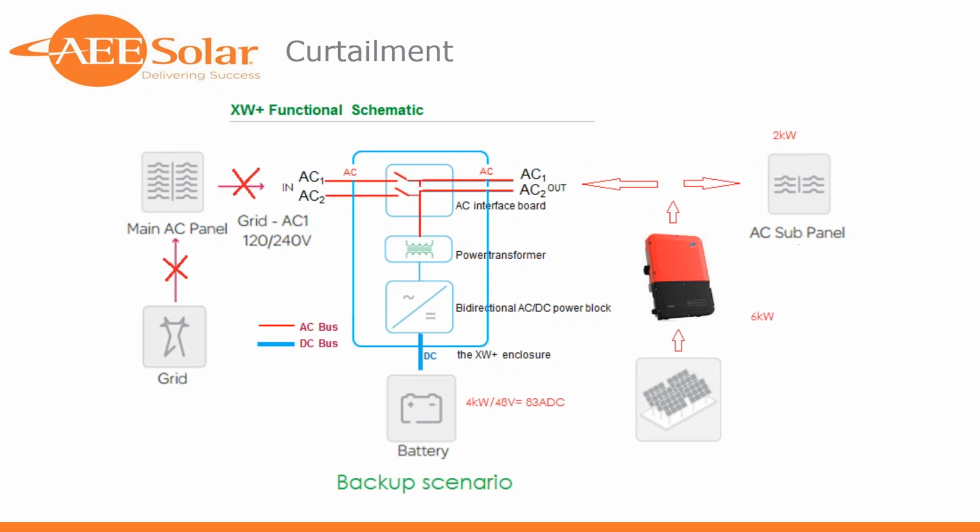This one was built and engineered by the University of Tennessee, and eager innovators that they are, they wanted to take this home on the road and show the people of Tennessee what they did. They had a 10 kilowatt array installed on the house for the purposes of the competition. They knew all of the places they wanted to take it wouldn't have an AC connection for them to sync up to. So they installed a battery inverter and a very small battery bank.